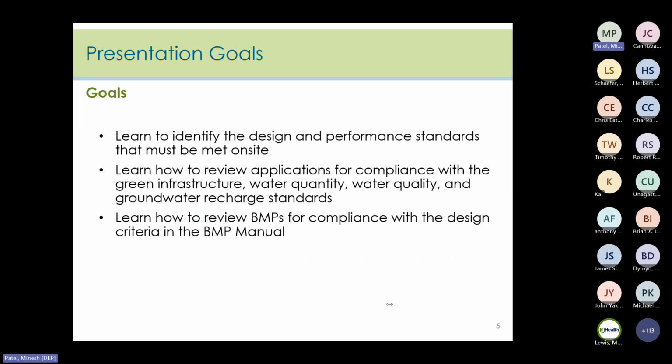So here are the goals of this presentation, which are, by no coincidence, the goals of a successful project review. We want reviewers to be able to identify the design and performance standards that must be met on site, review applications for compliance with green infrastructure, stormwater quantity, stormwater quality, groundwater recharge standards, and review BMPs for compliance with the design criteria found in the BMP manual.